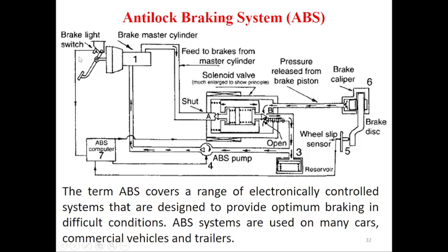First of all, on the upper left corner there is the brake light switch. When we apply the brake, this brake switch is on, at point 1. The master cylinder is here, and the master cylinder is fed with brake oil. This oil moves towards point A.